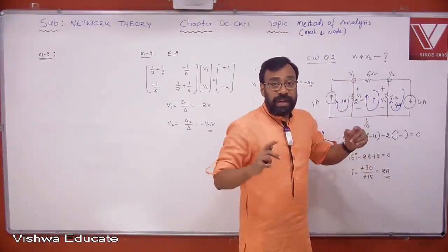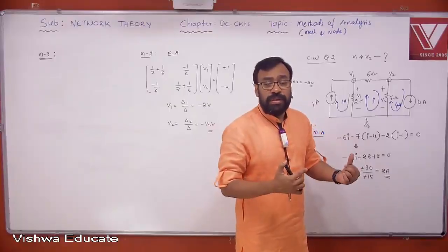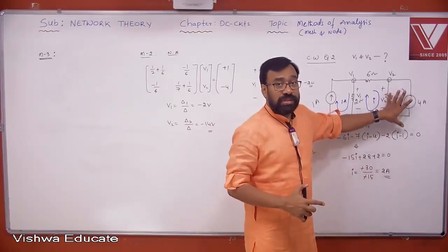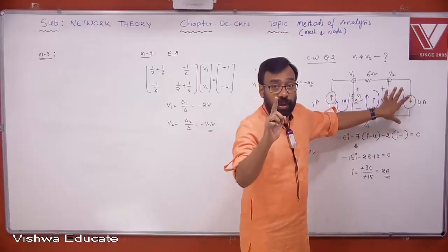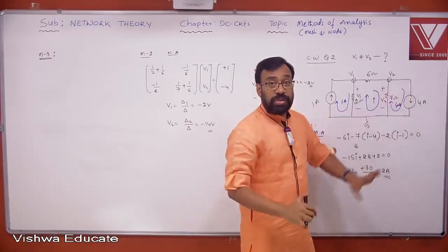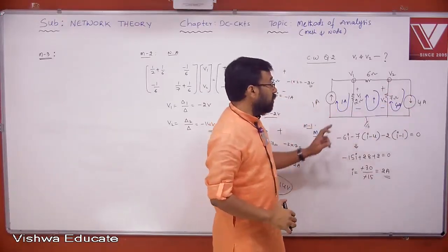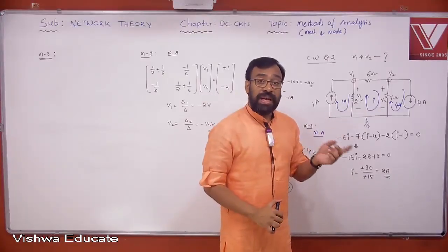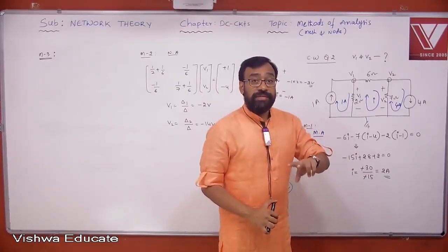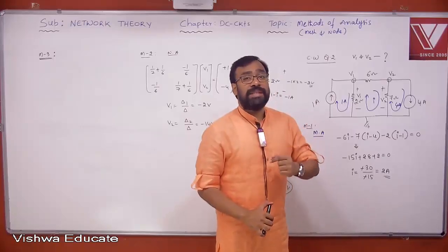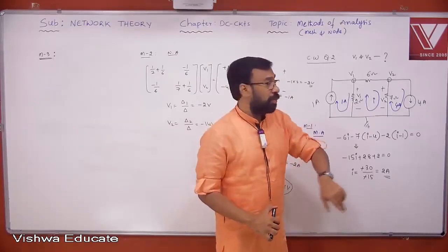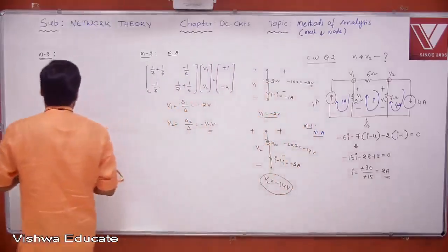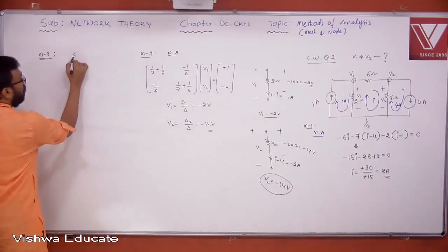But if given an opportunity to solve this network, use node analysis and utilize this transformation, and solve with only one equation. So minimum number of equations using mesh analysis is 1, and using node analysis is 2. Then if somebody asks to solve using node analysis, you can utilize the transformation and solve it by only one equation.